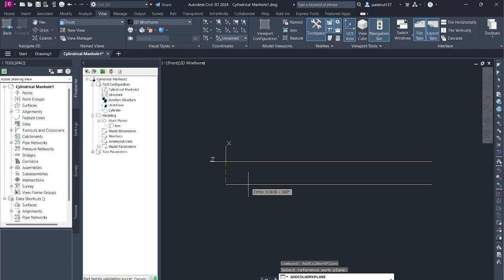The Equation Assistant dialog box is displayed. Select the Variable button to use the pull-down to select which structure parameter should match this work plane offset. Click SFH. Press OK to exit the Equation Assistant dialog box. The SFH parameter is displayed under the equation column in the Model Parameters dialog box.